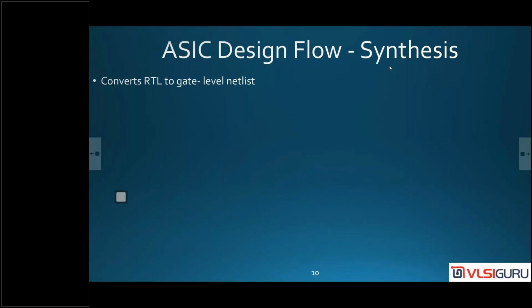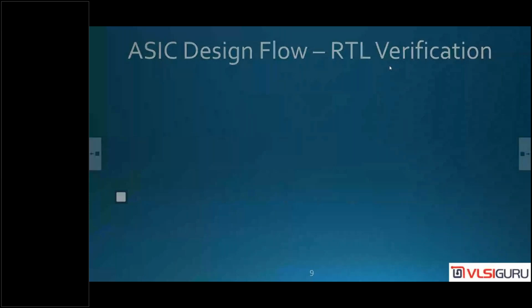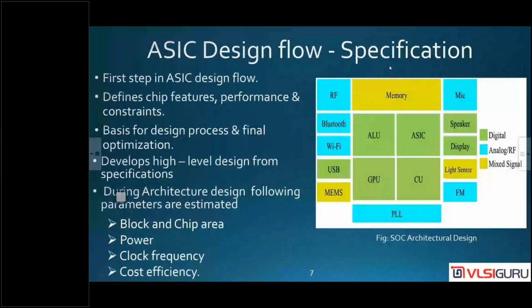See, RTL is in the RTL form. Convert that into what form? Gate level form. See here, RTL is written for different blocks. Right? So before coming to synthesis, there is an RTL integration engineer who will integrate all these blocks. Integrate means connect the blocks using Verilog, not by using metal layer. Using Verilog, you connect the blocks logically.